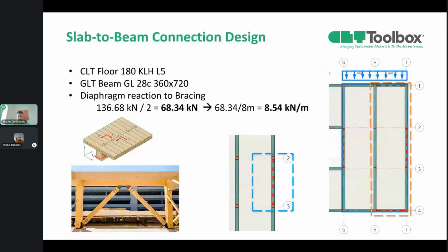Now, as we have pointed out some of the theory behind the calculations, we can discuss and show some of the application of these screws in our platform. From the previous episode, we designed the CLT diaphragm where we verified the slab thickness, but also calculated the panel-to-panel connections. We also calculated the forces from the diaphragm transferred to the vertical bracing.